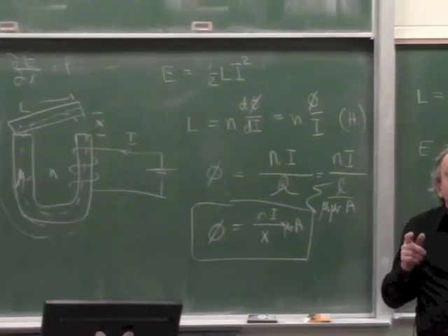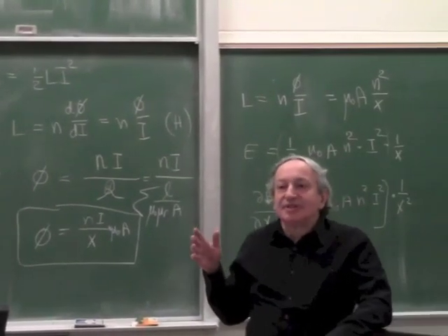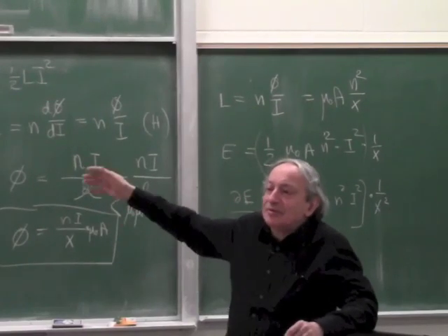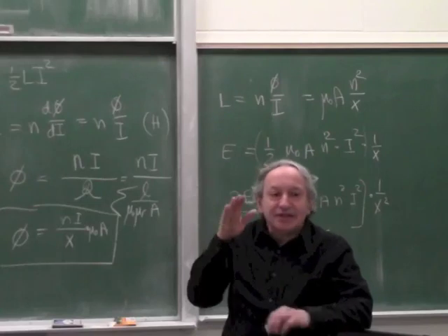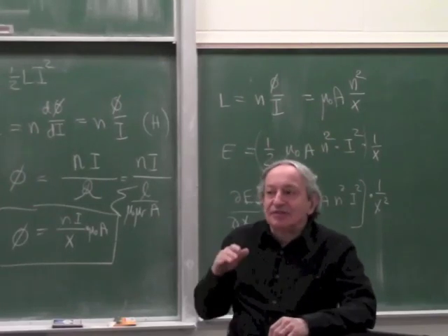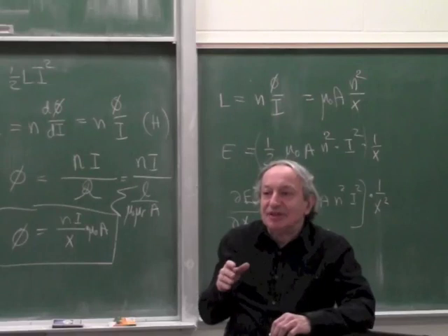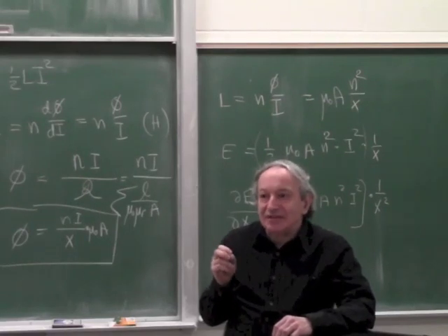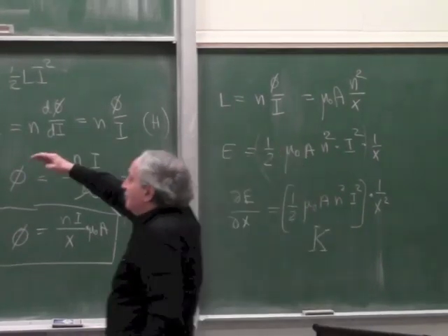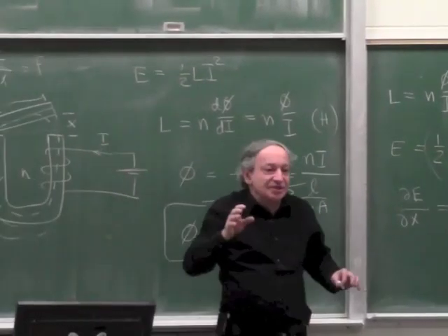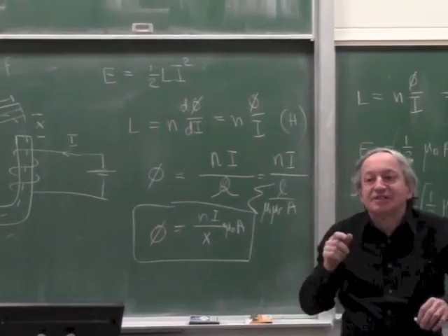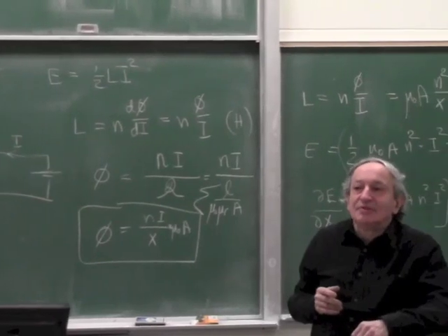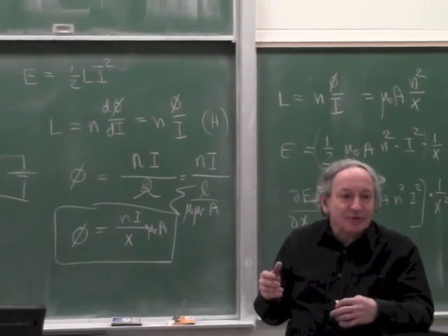Now, if the gain becomes very high, and all the other properties are the same, the mechanical properties, not the inductance, if the gain becomes very high near closure, you have to design the filters and everything for stability. So you have to design the system so that it's stable at the highest gain, where this armature is almost closed. You have to be very careful with the phase shift and everything, so that it will still be stable at the highest gain. Which means at a different gain, the system will be sluggish, underperforming.